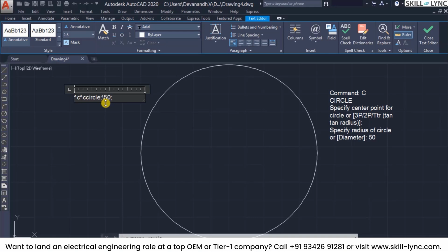We are cancelling twice so that it comes out of all the steps that might be in the previous command. And the next step is that we also include an underscore. You execute two cancel commands, and before the command you introduce an underscore so as to force the macro to use the English definition. That is, use only the circle definition so that it eliminates any issue. These are the basic special characters used in macros.